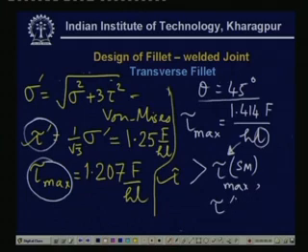Now, this is normally used in practice. Okay. Now, although this is almost a thumb rule, this is in no way an accurate theoretical result, but of course, it is very, very useful, and this is called the unified formula. So, let me write down this formula again, which will be the basis of calculations for the strength of welded joint for a transverse fillet weld.